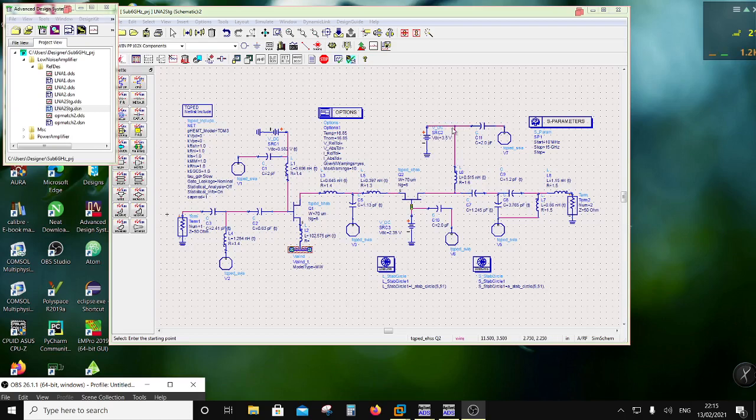And then there is a voltage division, so there is 3.5 volts over here, and this has been designed to be 1.8 over here. So basically this stage was designed with the 1.8 drain voltage, and this stage was designed between 1.8 and 3.5 volts. So that was the division, and the currents in both the stages have to be the same, because that's the only way you can hold this voltage. So you design this with that in mind.